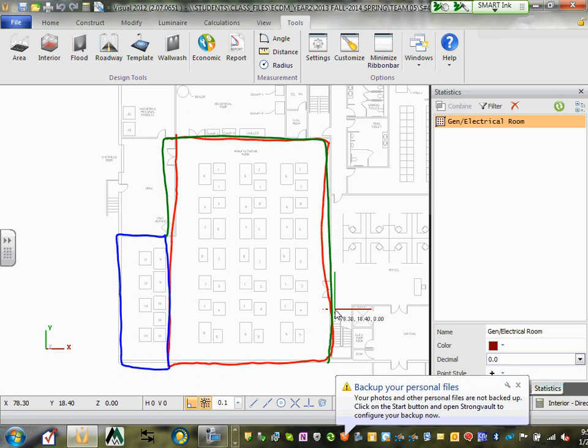Your model is going to go like here, all the way, green. Build the box. When you build a box, that's through construction. Here we construct, we build that, and name it. Separate. Put the calculation zone at the bottom at 2.5, and then grab the fixtures that you calculated on the side. Only the fixtures. Pick one fixture at a time, drag all these fixtures and drop them here. They will be at the same height.